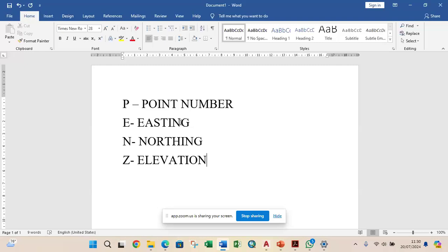So how do you know when the surveyor is doing the right thing, when he's working on a project and you want to checkmate him? There's a tool: you can use Google Earth or GIS to do this. In Nigeria, we have 2 datums that we normally work with. We have the Minna datum, and we have WGS 84, World Geodetic System.